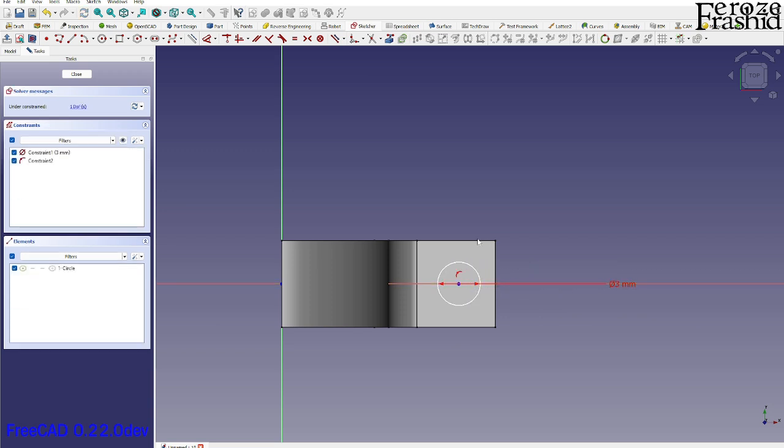And then I think the corner was rounded, so I can do that with the fillet. I'm going to take this point as my external reference and say the distance between these 2 points will be 3.